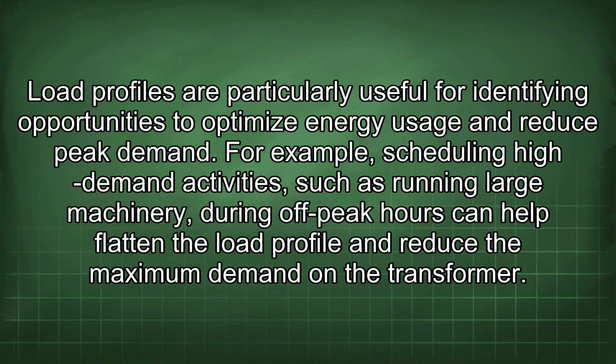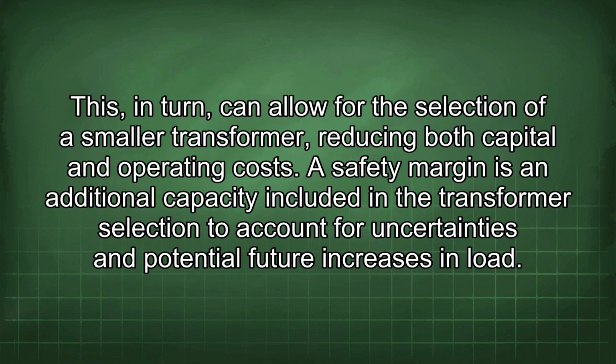Load profiles are particularly useful for identifying opportunities to optimize energy usage and reduce peak demand. For example, scheduling high-demand activities, such as running large machinery, during off-peak hours can help flatten the load profile and reduce the maximum demand on the transformer. This, in turn, can allow for the selection of a smaller transformer, reducing both capital and operating costs.